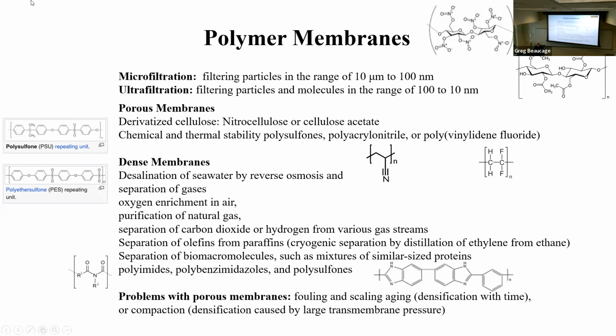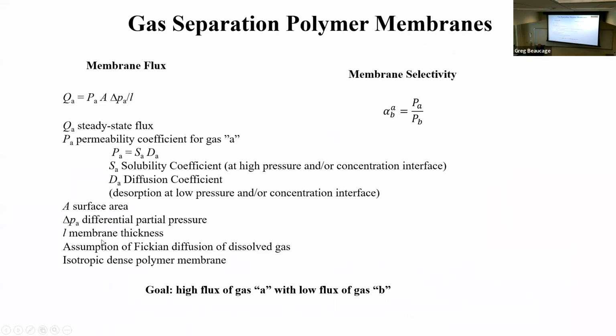So you can look at the free volume of the polymers and then somehow get the gas to absorb, or to solvate, into the polymer and then transport across it. And if the rate's different for those two processes, you can separate the gases, right? So you end up with this: the transport membrane flux.